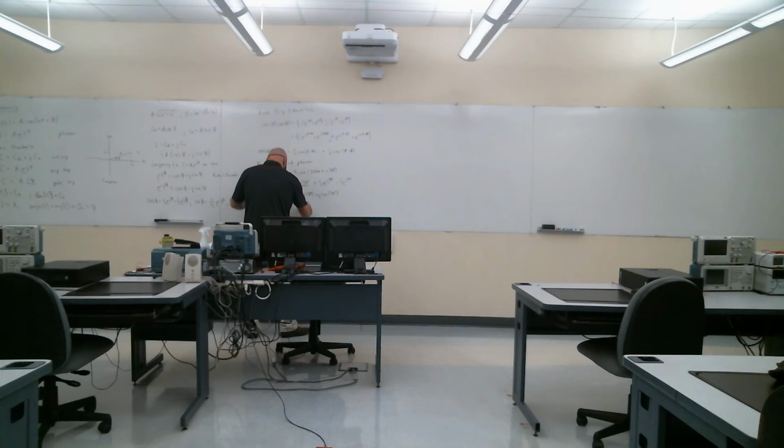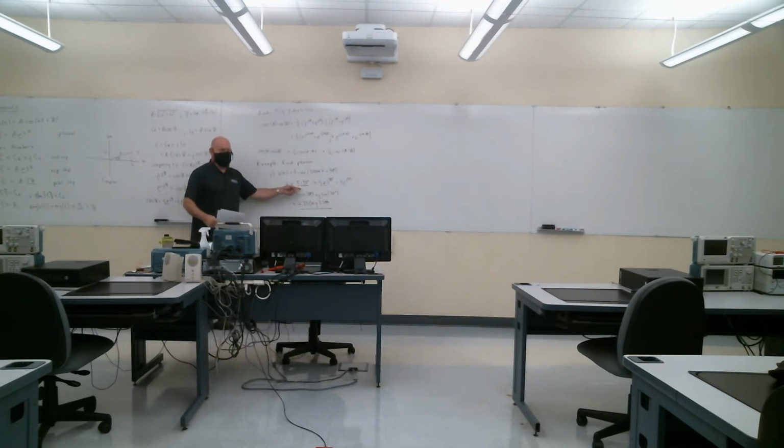And that becomes 4.330 plus j 2.500. Do you have to do all of those? No. The first one is fine. If you're asked to find a phasor, these are just different representations of the same number, right? When you're adding complex numbers, at least by hand, it's most convenient to use the rectangular form, because you add the real parts, add the imaginary parts. If you're doing it by calculator, it doesn't care. It'll just happen.